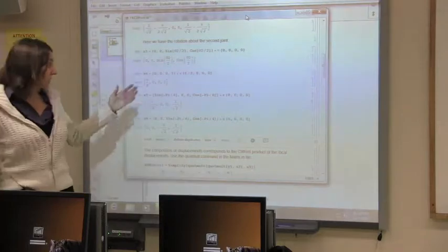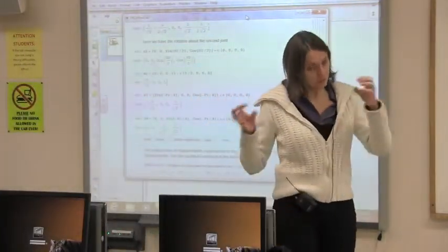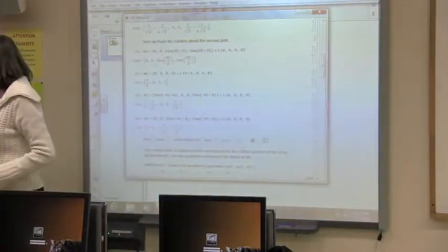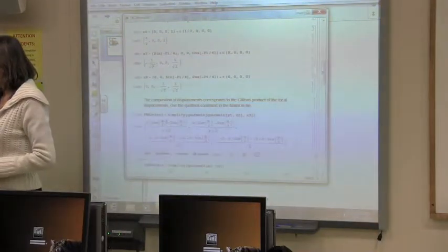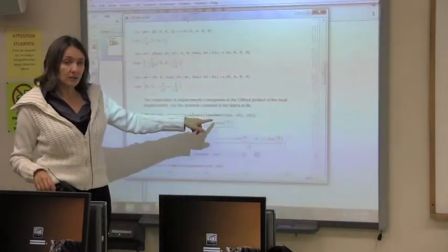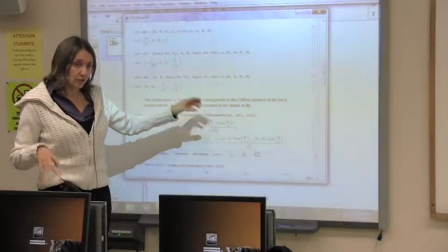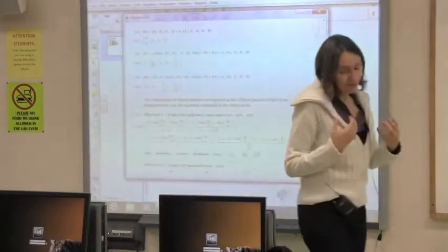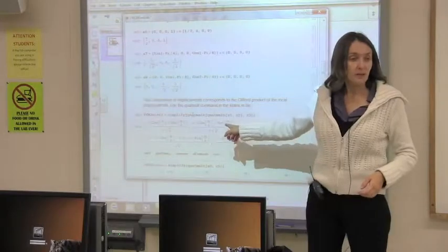Now in order to create the forward kinematics, we just need to compose all these local displacements, which means multiply the transformations. The way I did it here, I did it in 3 parts, so I went up to joint 1. You get this, and this is the command we use, quadmult. This is from that matrix.m file. It multiplies 2 dual quaternions or 2 quaternions. So it does the Clifford product. Because it's our function, we have defined it, we can only multiply 2 elements at a time.